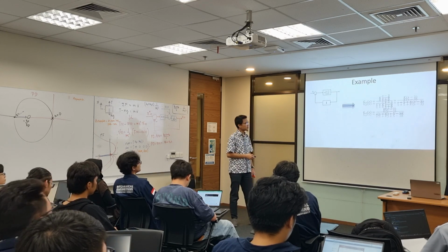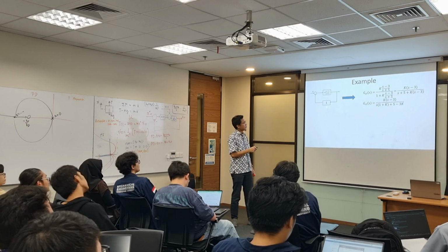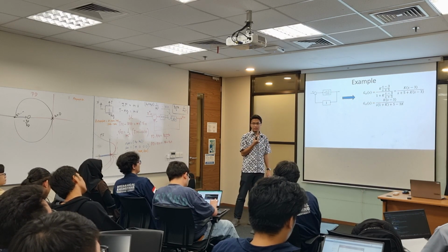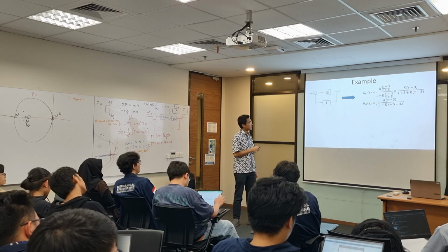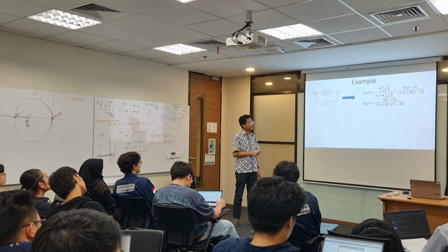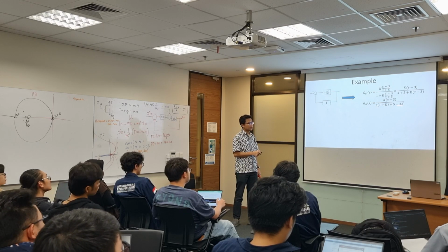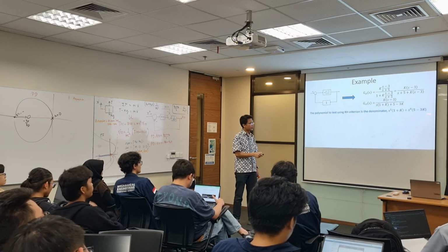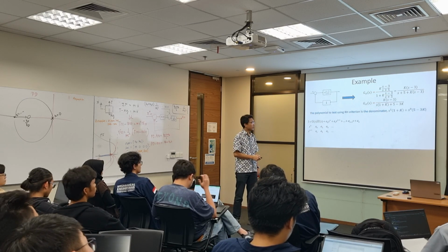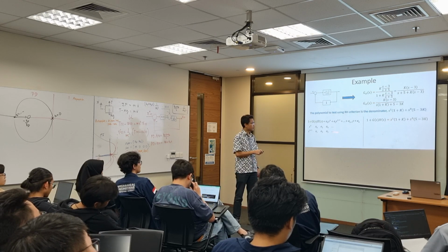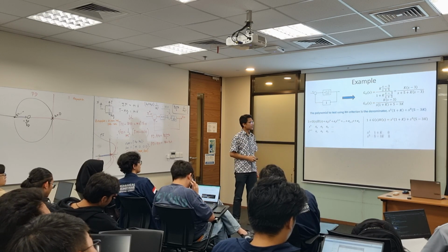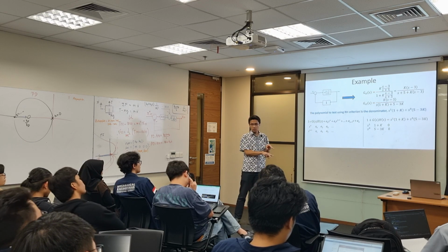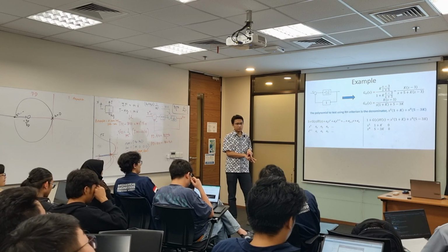As an example, if we have a system like this and we want to check the stability of the system by checking what's the value of K, then we are interested in the denominator. So we take the denominator as the polynomial to test and make the Routh table. Follow the Routh table convention, and because this is the power of 1, we only have 2 rows of the Routh table.